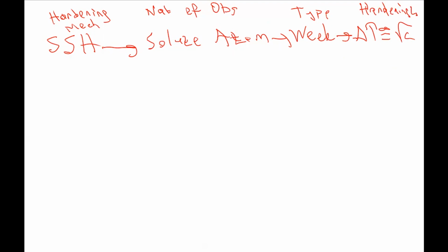We've covered precipitation hardening, and we can divide precipitation hardening into two. What are the two categories of precipitation hardening? Roa, what were the main categories of precipitation hardening? I can't remember right now. With small particles, right? With coherent particles, deformable particles, and with large particles.